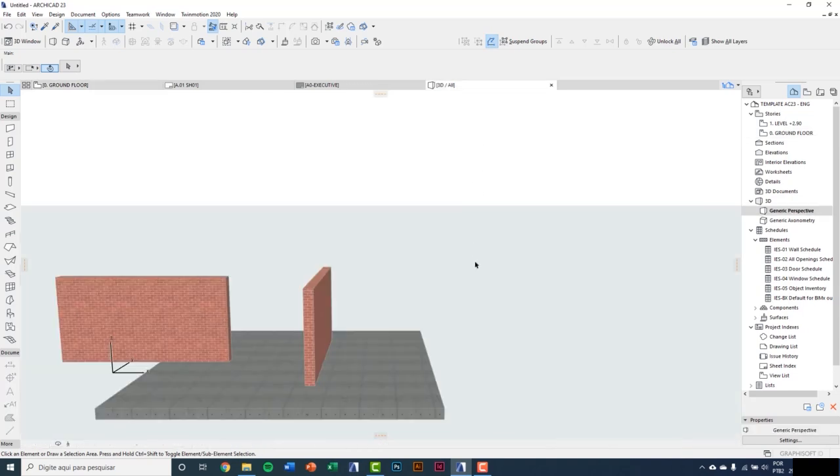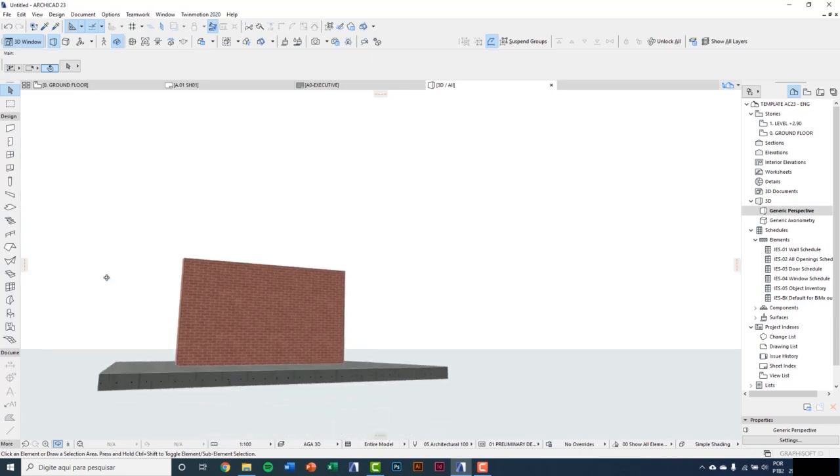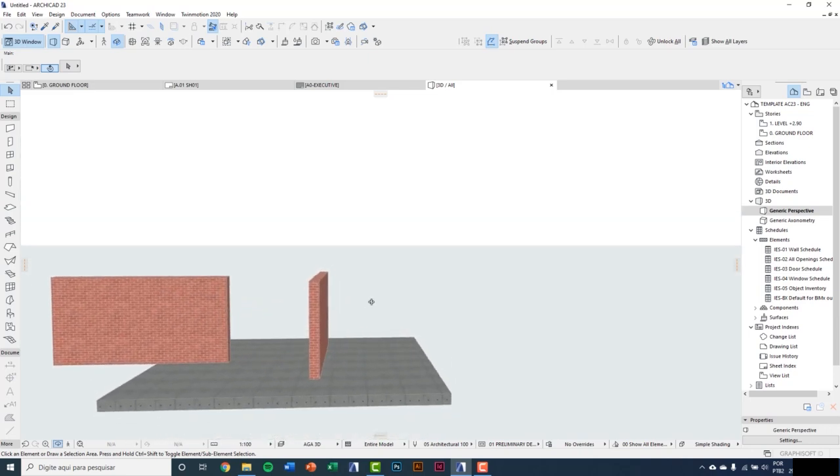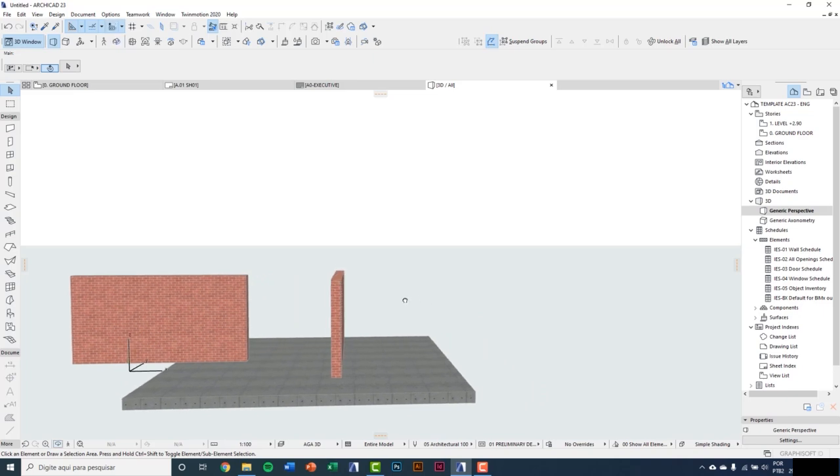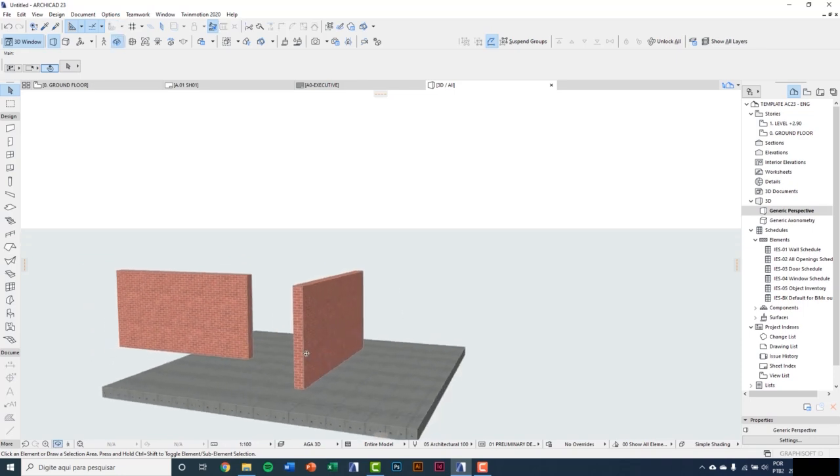On 3D, there is the orbit command available in this bottom bar. Here I have orbit. And using orbit, you can click with mouse left button and rotate it. Pressing the mouse scroll, you do the pan, dragging the model. Another option to use the orbit command is using the O key. So pressing O, you have this shortcut to the orbit command.